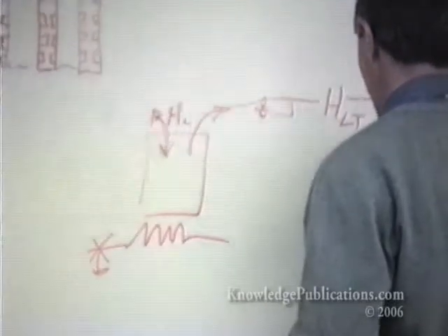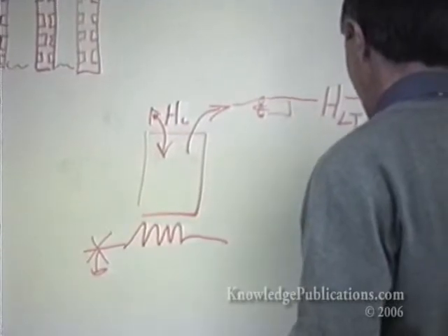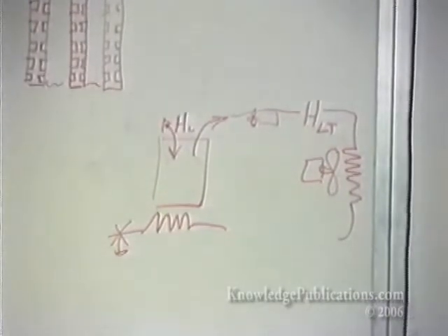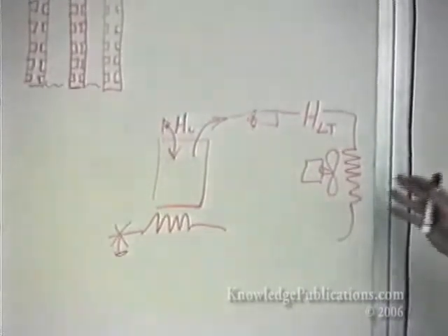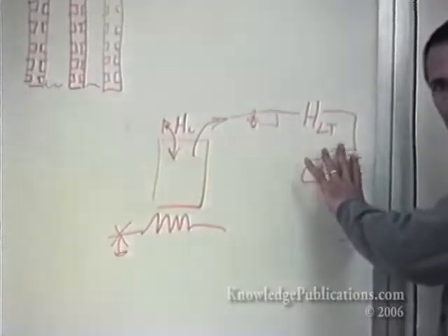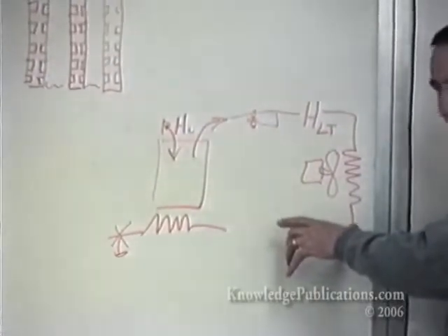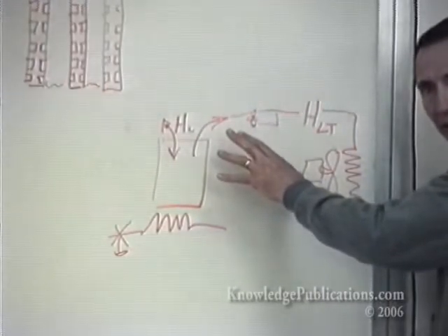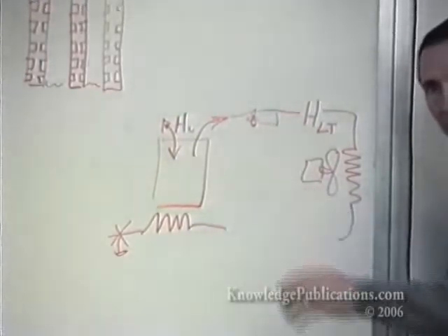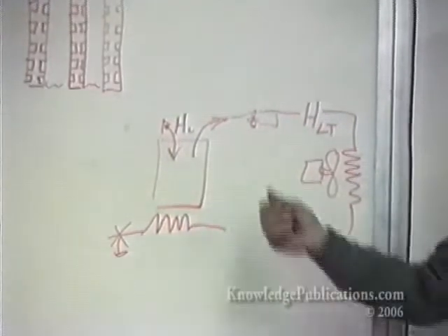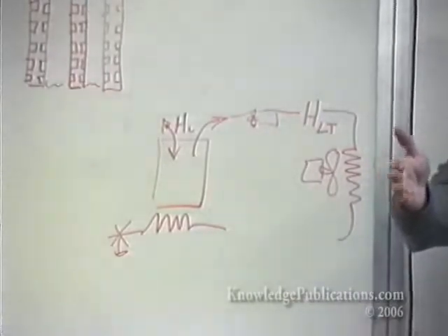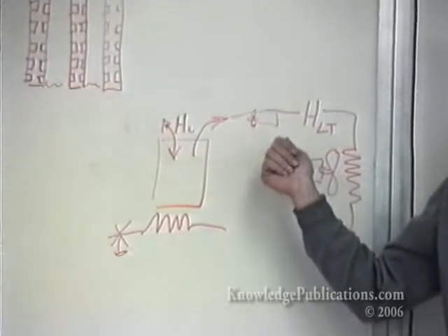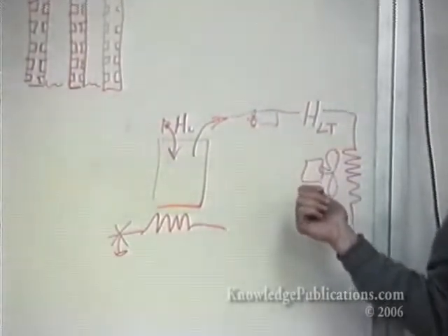You take that to a heat exchanger, run a fan across it, and cool the car. What are you talking about? We're getting our cooling from the energy of expansion. Yeah, the expansion is producing low temperature, which we use as a heat sink for cooling the air. What's the turbine for? The turbine is for taking energy out of the high-pressure hydrogen and doing the expansion to low temperature. So it's basically what we use now for an expansion valve. Well, you could put an expansion valve in, but this is more recovering. This gets back more than just the expansion valve. You get the expansion, but you also get cooling, a heat sink for cooling as a result.